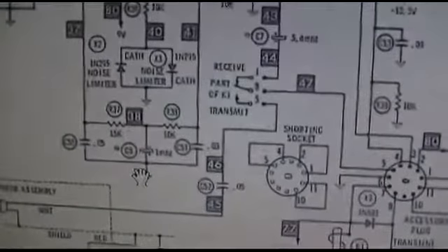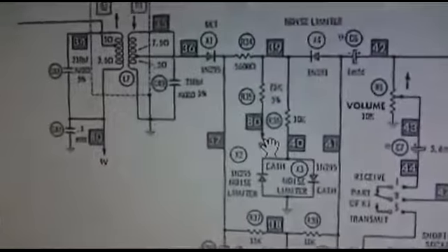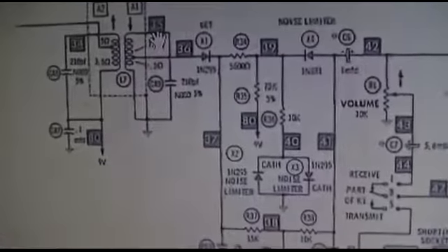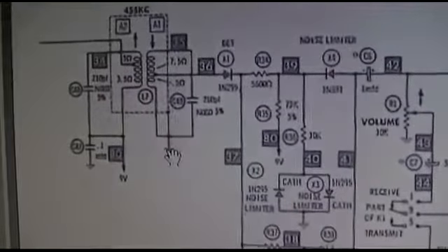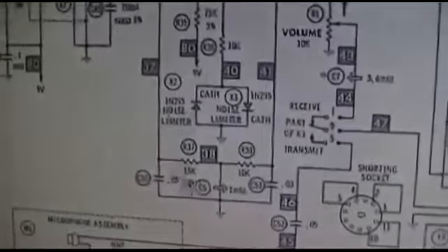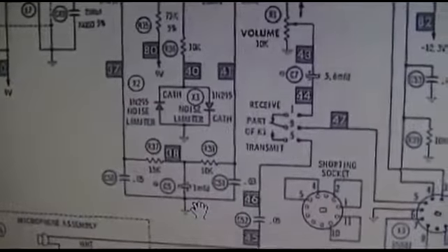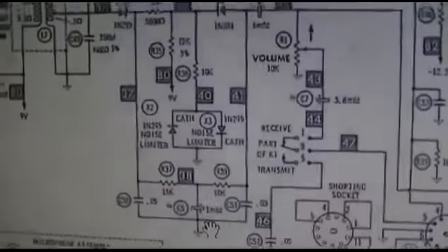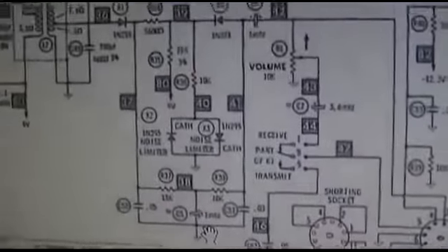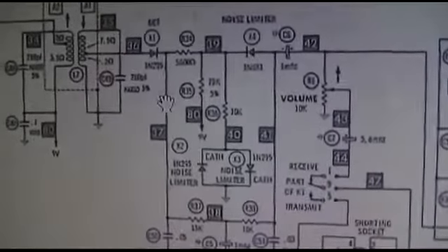There's this capacitor right here, because we got really stout signal on these two, and I don't know about on the other side of this detector, but what would this do if this capacitor was shorted to ground? That's a good question. Maybe I should check on the other side of this diode.